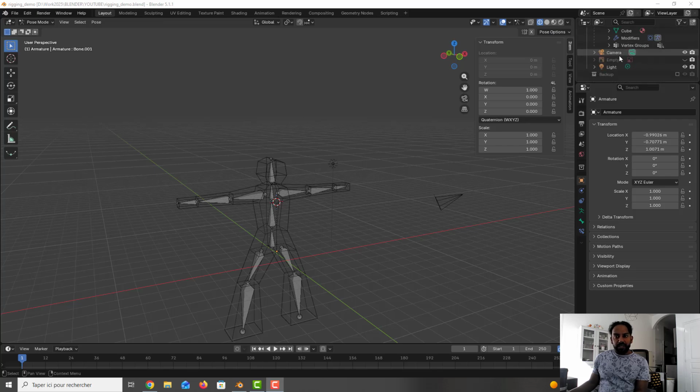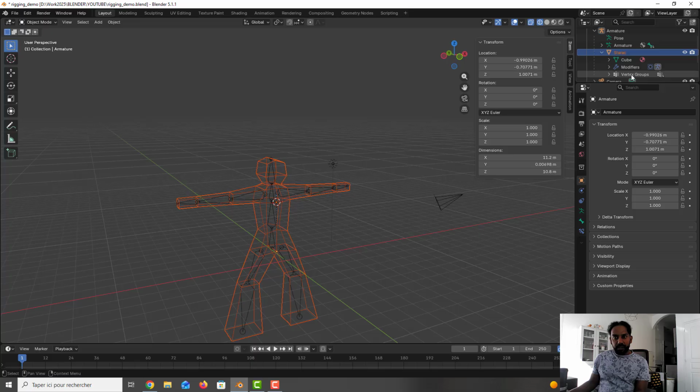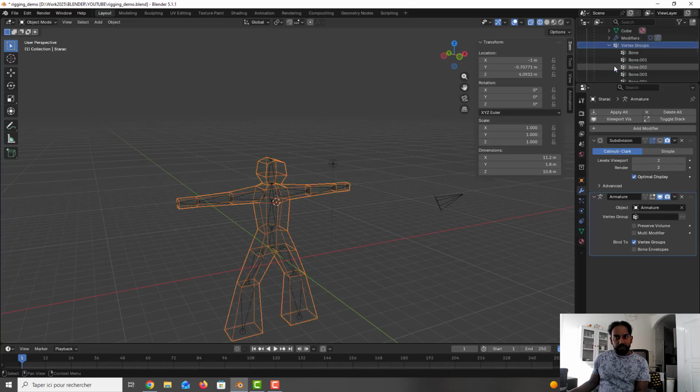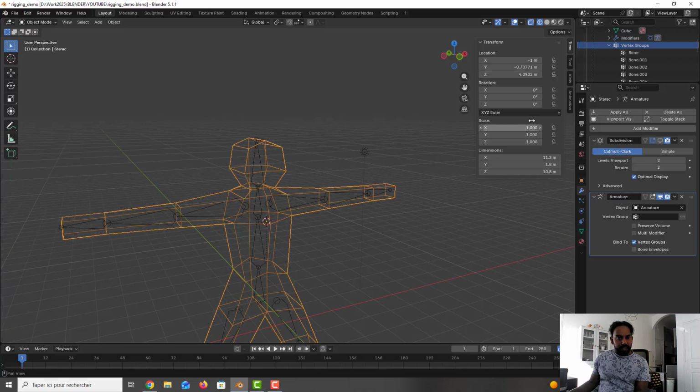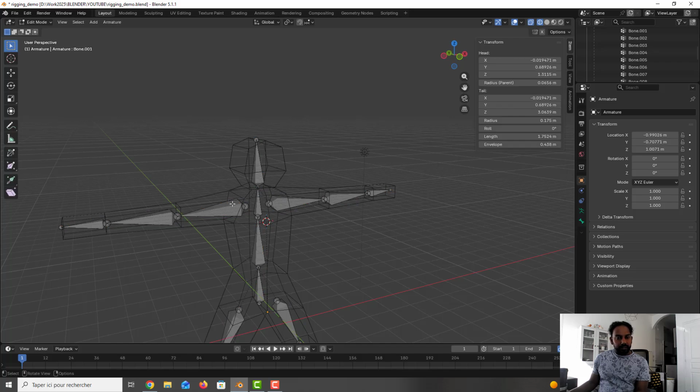Okay, we will fix the weight. So I will go to the mesh, as you can see here. We can exit from the pose mode to the object mode, like this, and we can go to the vertex group. And I will select, for example, the bone here. It's better to name every bone, but here it's the tutorial, so we can see that directly. So I will select with Tab, and we can see this is 11, and this one is 8.